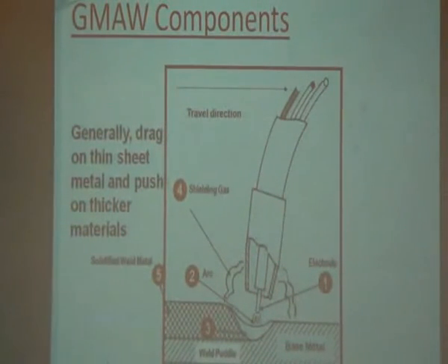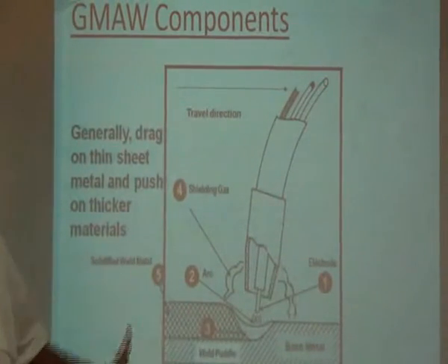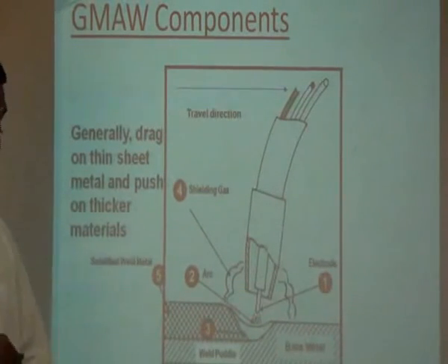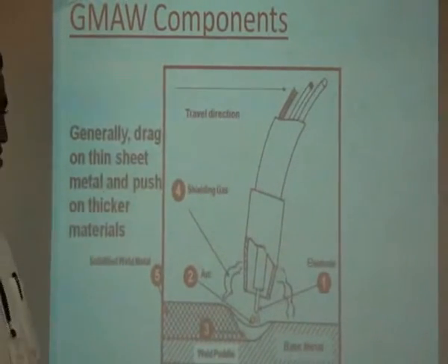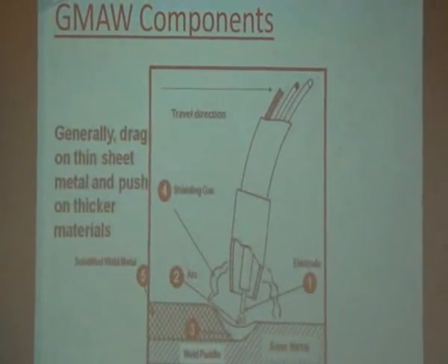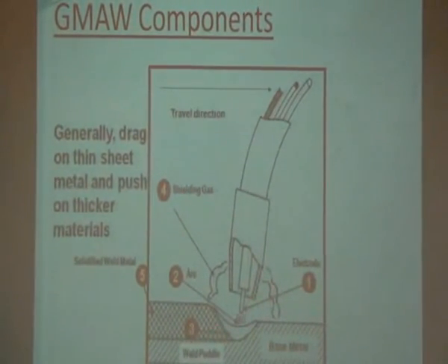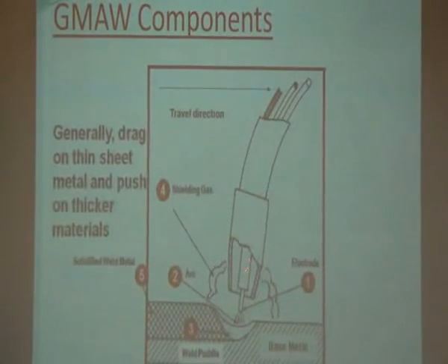So when you compare with the TIG welding process, the skill required here is not as much, but controlling the torch is very essential, and the welder has to have skill in this particular aspect in the case of the GMAW process. And here you will see that the shielding gas protects three things: the torch, the electrode, and the molten puddle.